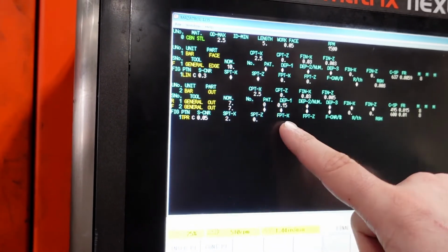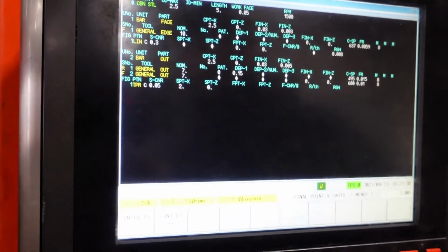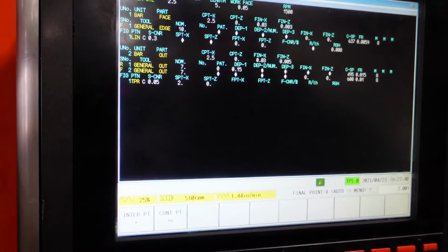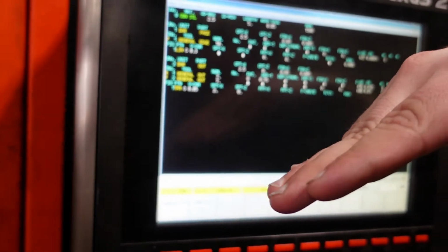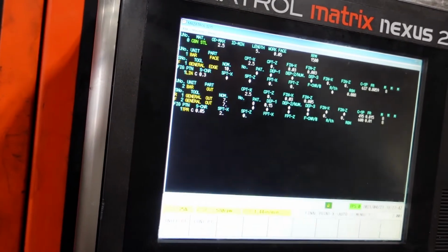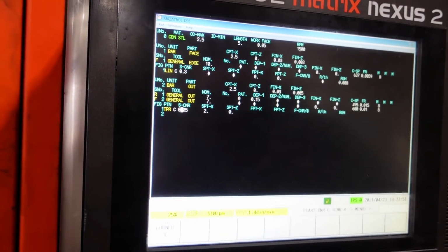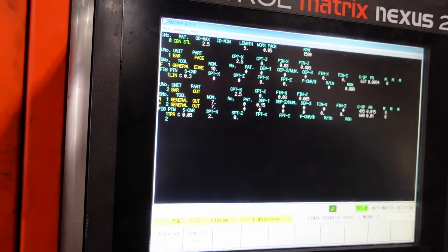Right? My finish point in X is going to be, say, 2.001. Say I have 1 thou taper and I don't want it in there, and it's tapering down. Now I can always make it go up 1 thou, and it will level it out across these 3 inches. Oops. Because I wrote 3 there. 2.001.